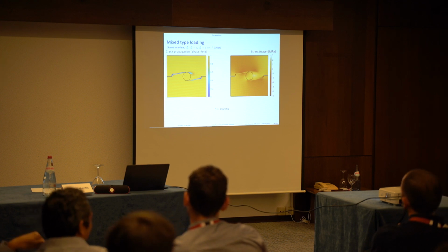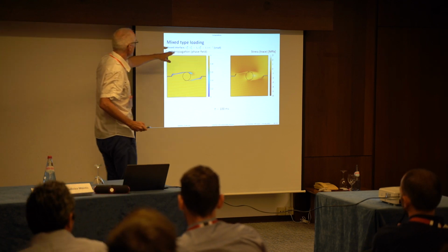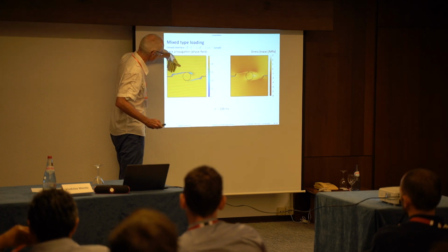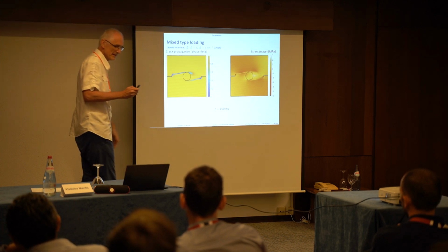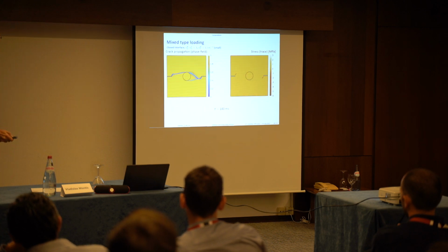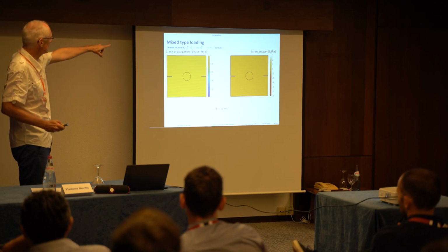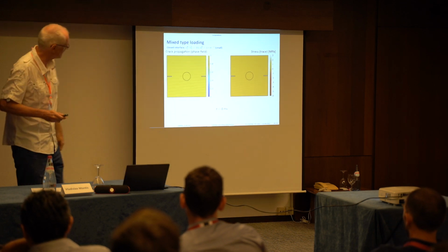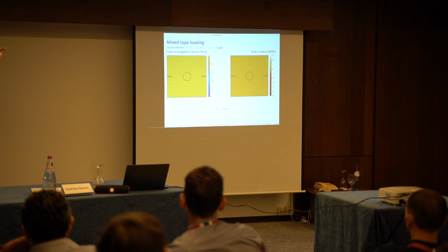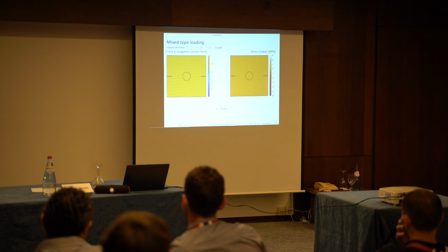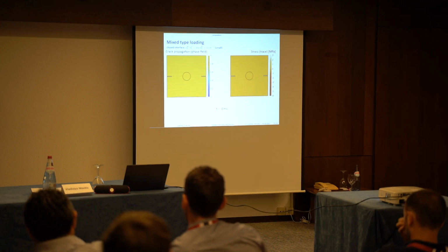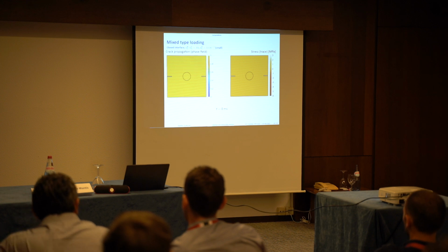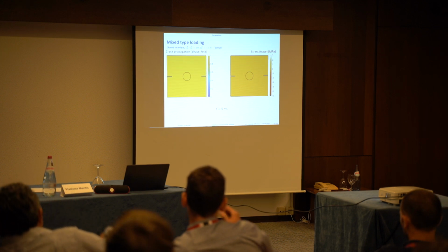So this is the influence of the inclusion. Again, with a small value of the ratio, there is more or less a crack due to shear. But generally, when we increase this value, again, we can compare the small value of GC at the interface, the first one, and later we will see the last picture when we have a large value. So with the first one, we will see the interface crack. And the other way, we won't see the interface crack. Nevertheless, there will be some crack that appears in the material due to different material parameters of the inclusion and the matrix.